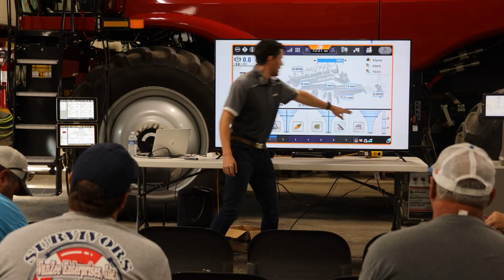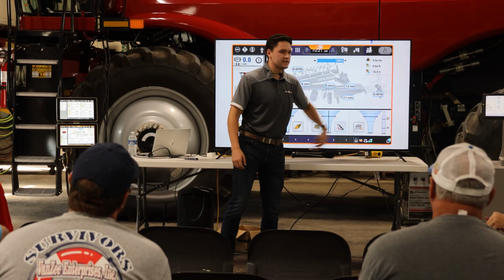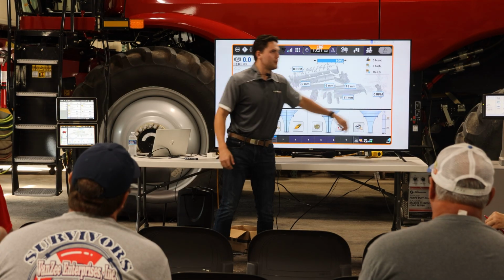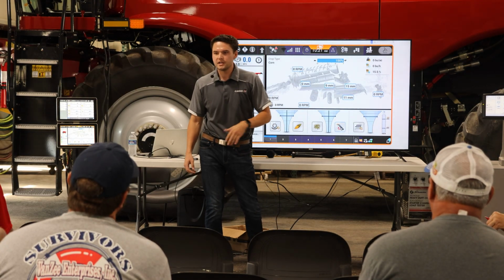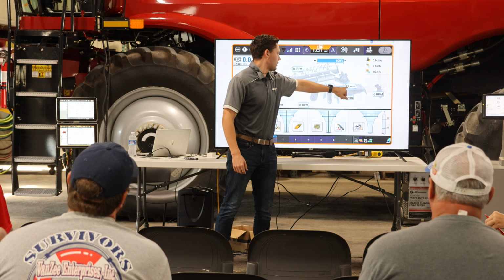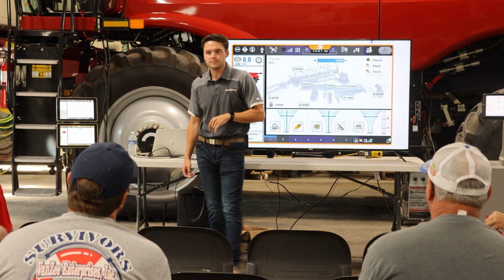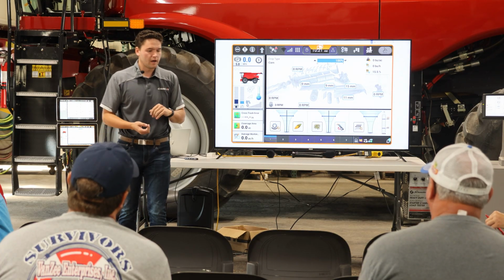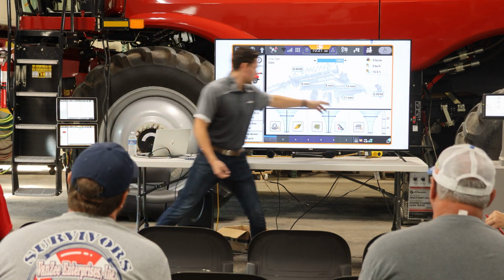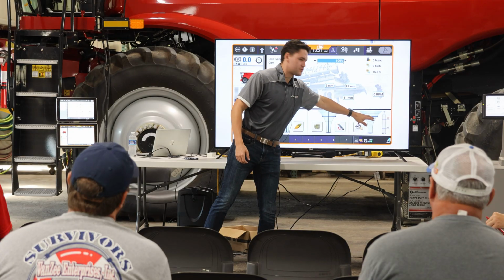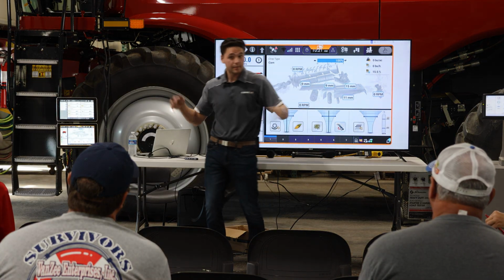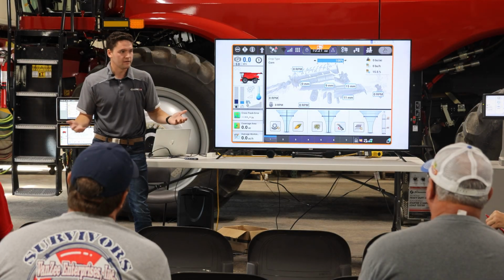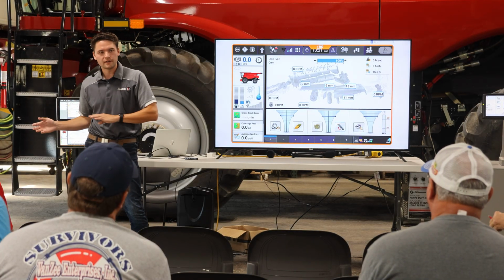We went up here and we made an adjustment. So let's say in that scenario, that's exactly what we did. It got to our trigger point right here. It went up, but before automation can make a change, we decided we're going to open up the upper sieve. In this scenario, we're at 15 millimeters. Let's say we opened it up to 18 millimeters, so we raised it by 3 millimeters. And the result is it went back down to a desirable range right here on our trigger point. So everything's happy, everything's running good, the funnel fills are where they need to be, and everything's fine, right? Everything keeps going and nothing changes.